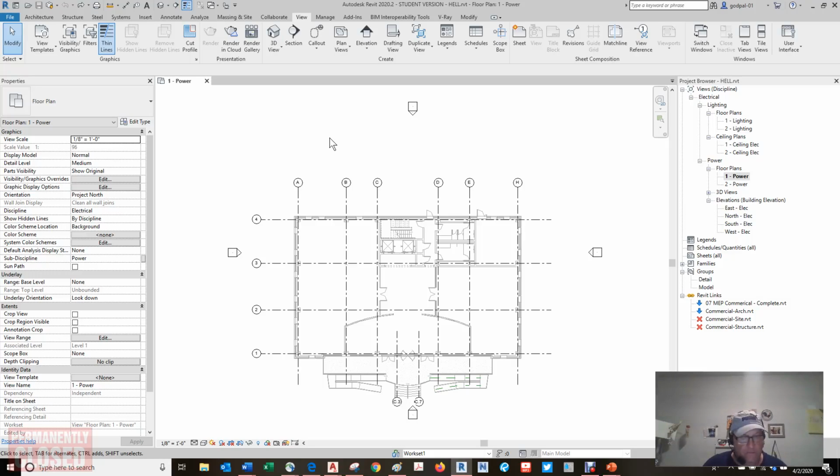In any event, if you decide to use tiled views when you work in Revit, you should be aware of a subtle limitation. You'll be able to zoom into only the extents that are defined by the drawing area. If you want to get around this limitation, here's a helpful tip. Create a new sheet, but then delete the sheet border. This is now a workspace for any view of the project. Just be sure to label it as a working sheet apart from your documentation set.